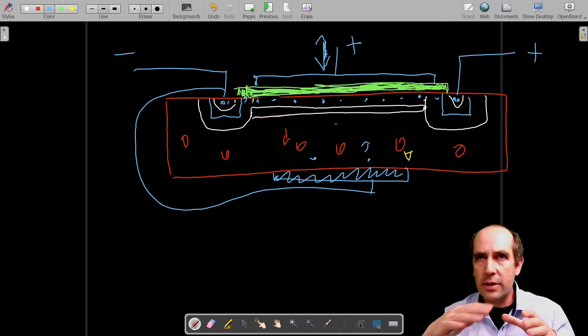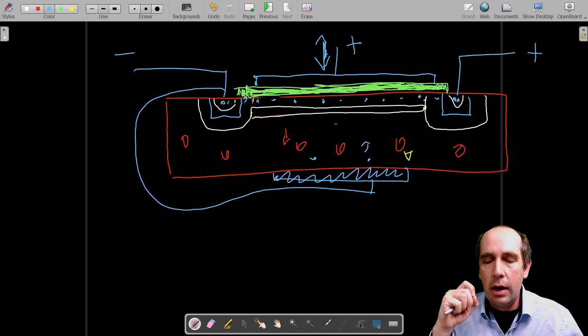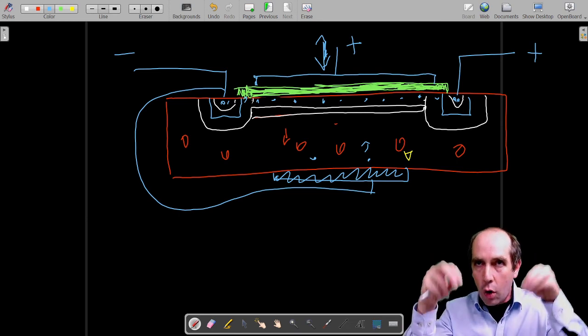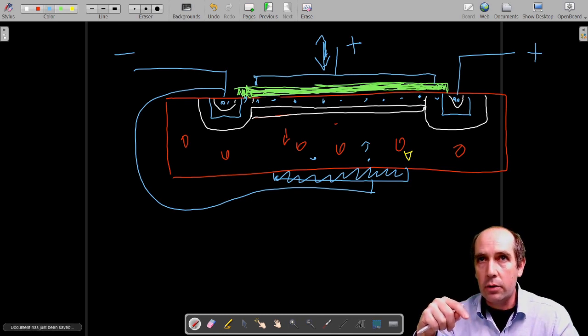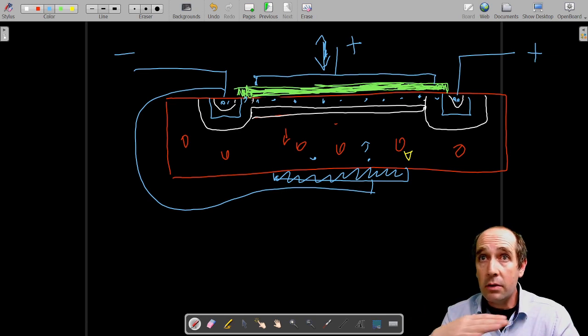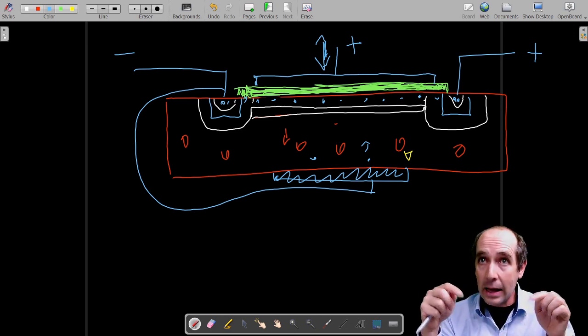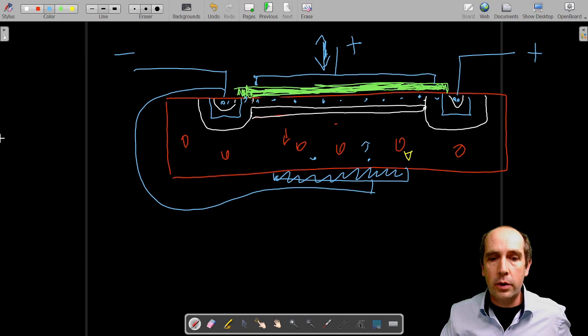If you have a wafer of semiconductor and you can, let's say, drill these little holes and put the N-type material, for example, or not drill the holes but just dope selectively some regions of the P-type semiconductor with N-type. You can put millions and millions of these and just interconnect them with little wires, and this is the way integrated circuits and all the digital logics and processors in your computers and your phones and everything work. So this is actually the type of transistor that is used for digital electronics and for integrated electronics.